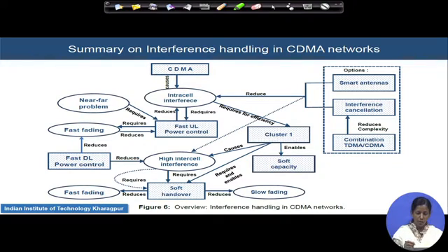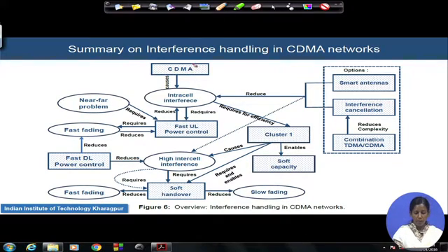Let us revisit. In a CDMA network, the network causes intracell interference. This intracell interference is coming because of the multipaths in the wireless channel, and also because in the uplink direction the users cannot be synchronized. Because of the channel, the orthogonality of the codes cannot be guaranteed because of the high delay spread involved, so you are getting a lot of intracell interference at the receiver.